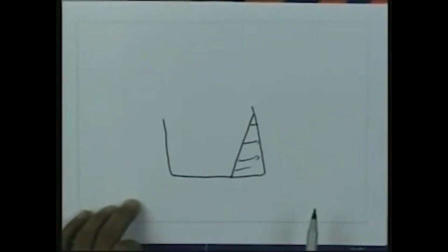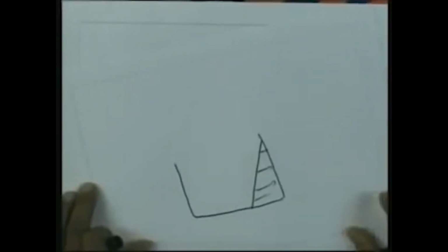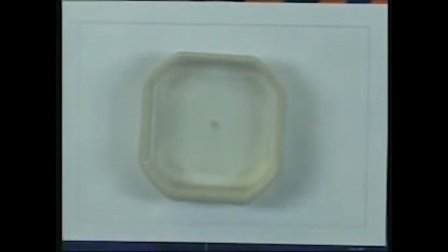So, that is one of the important features which we will be using, and the second one is that the pressure at any equal depths in a continuous fluid is equal. Say if you consider the fluid in this basin or container, then the pressure at any equal depths, here or this location or this location, in a continuous fluid is equal. And the third important feature which we have discussed is Pascal's law.